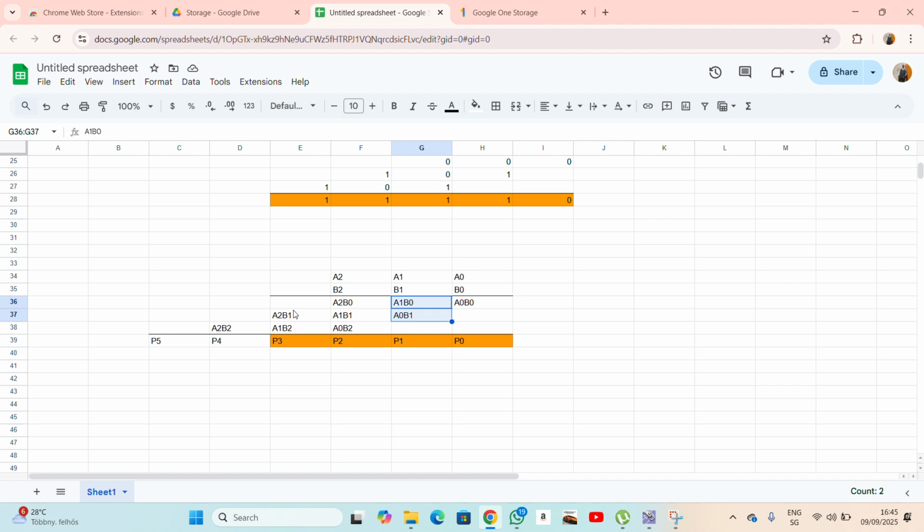Then the result of this addition, the carry out, is going to be carried to the next column, and we are going to be adding 3 variables, and that's why we'll need a full adder here. And then the result of this will be carried to the next column, and that's why here we're going to need a half adder, and then finally the carry out from this point is going to be brought to the next column, and it will be added to nothing, so it will simply be dropped down here as P5.